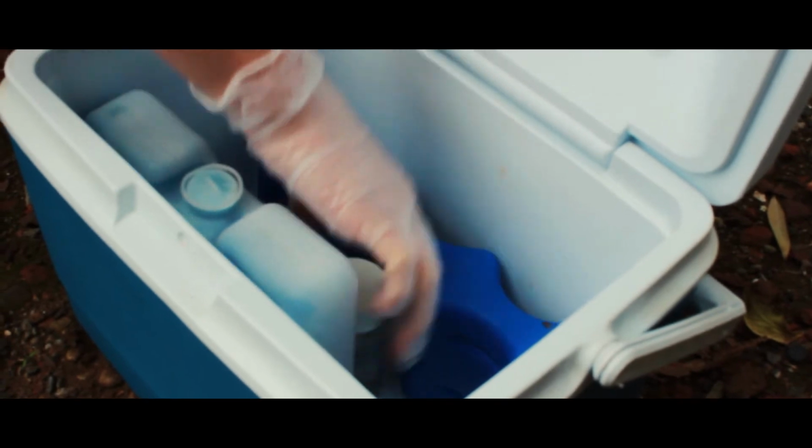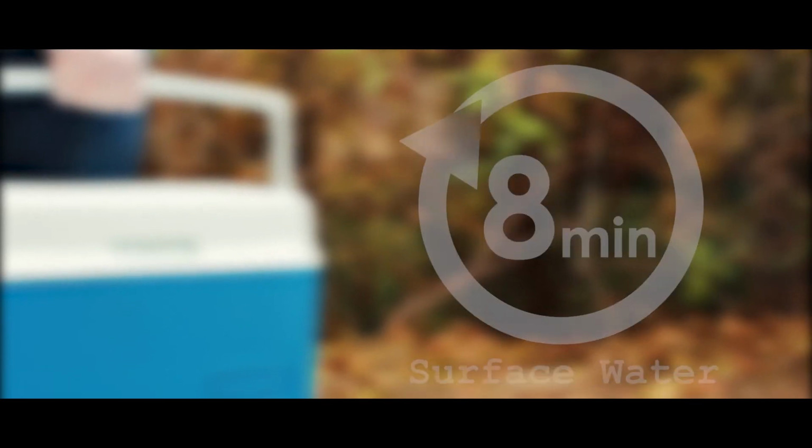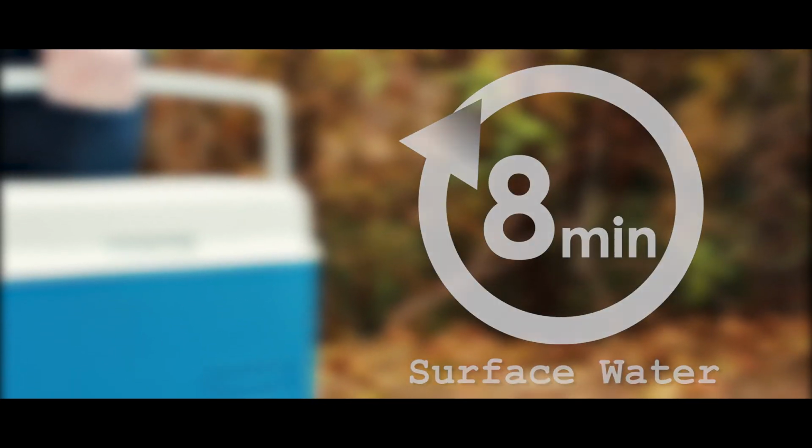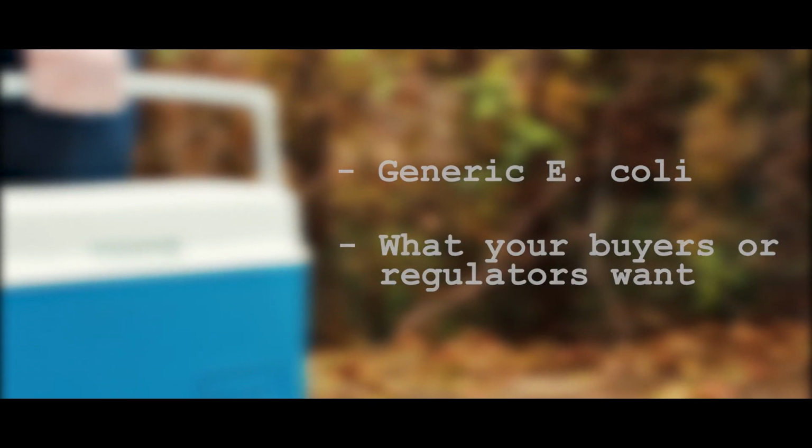How to collect a water sample. Step 3. Transport the sample. The samples should be placed on ice immediately after collection. Samples should be received by the contract lab within 30 hours for groundwater and 8 hours for surface water, or according to the lab's directions. Samples should be tested for generic E. coli or for what your buyers or regulators require.